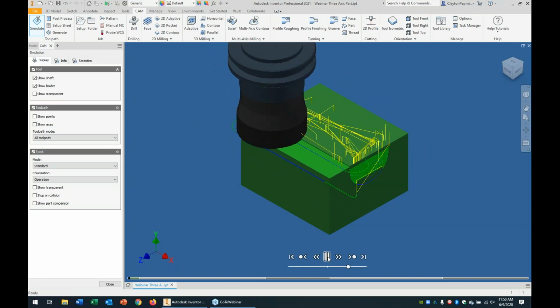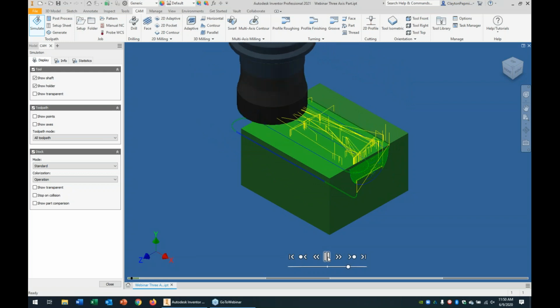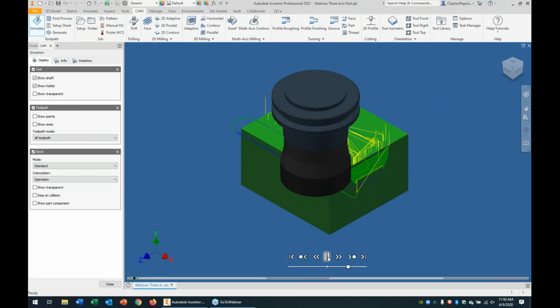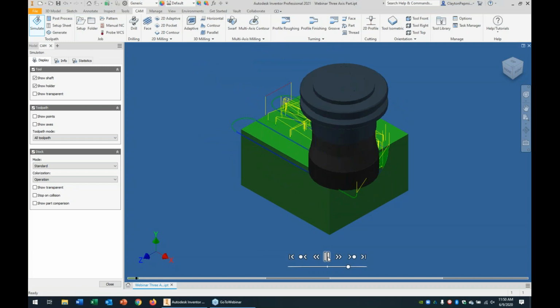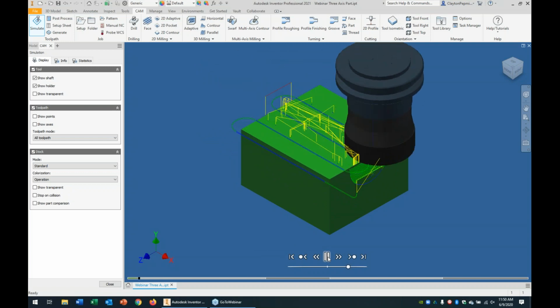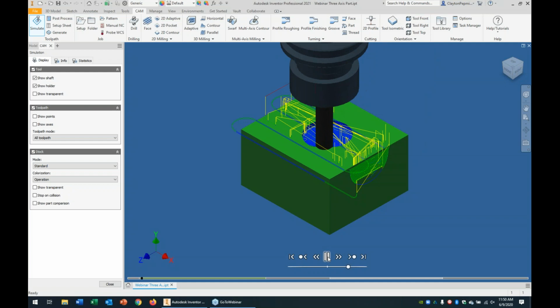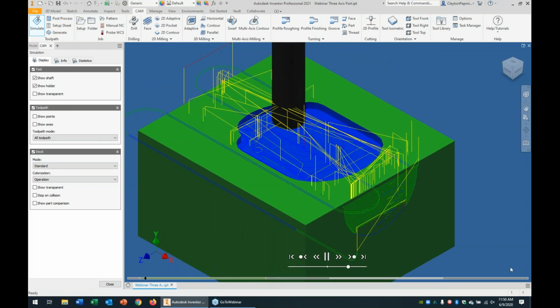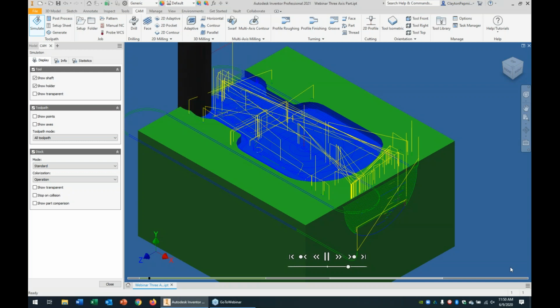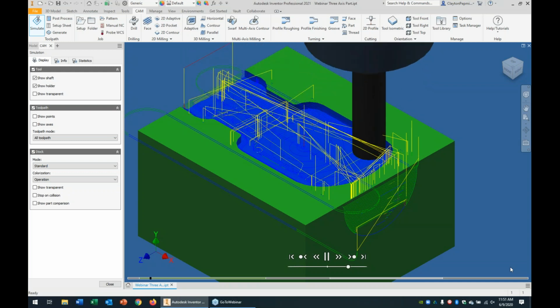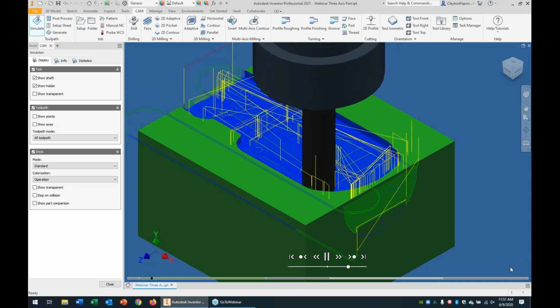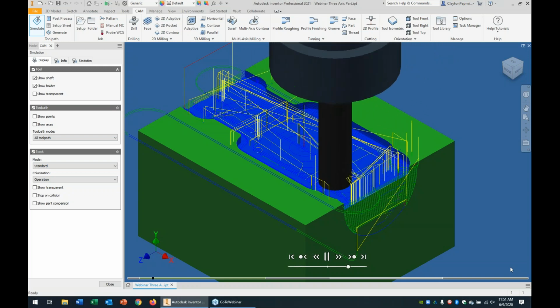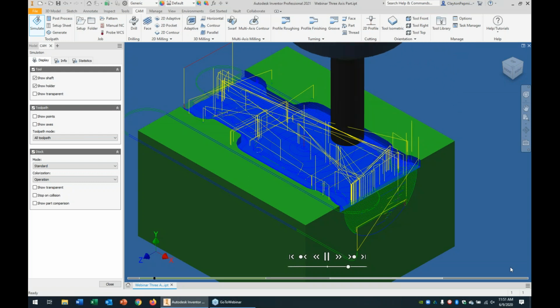But to look at this from a machining point of view, hit play on that. You can see very quickly I'm using that big old 2-inch shell cutter to face the top of this. We do that in 2 passes. Here's that adaptive roughing. Trying to get it in good and close so you can see it. Again, not at any point in time does it bury that tool. Anytime it sees a corner or place where it can get in trouble, it starts swiping at it. Again, it's to maintain that chip load and to save the wear and tear on your tool.